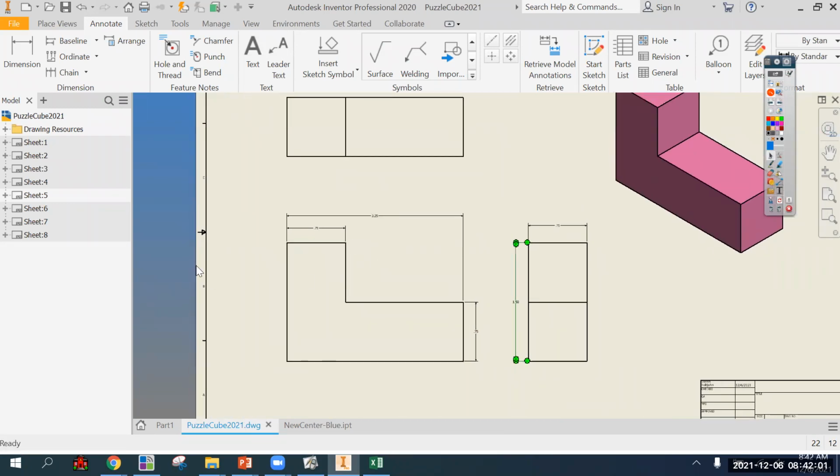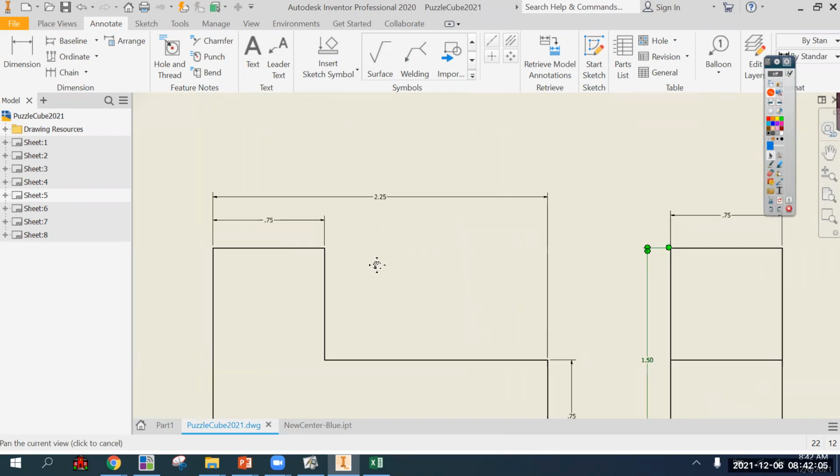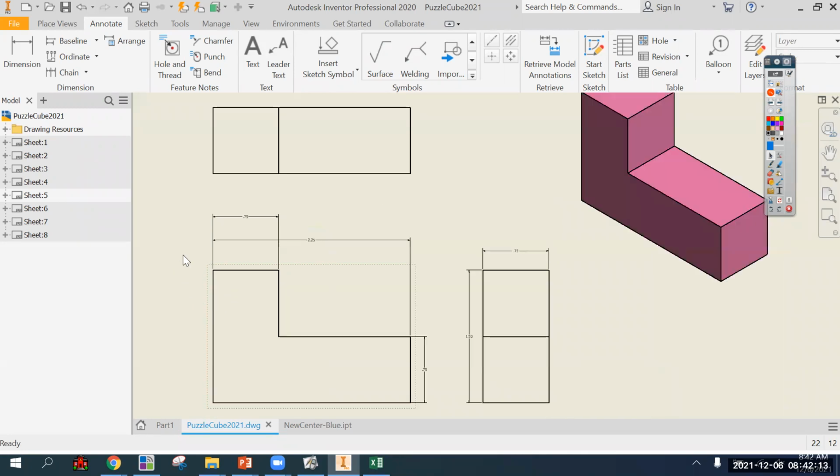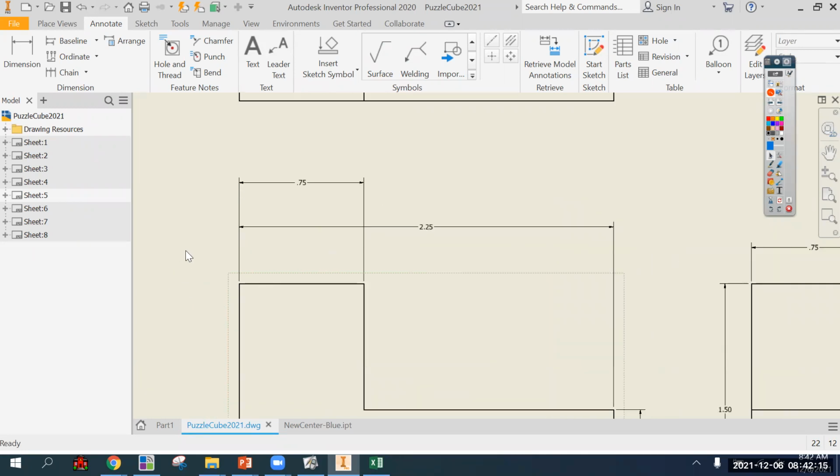So our method of working left to right every time something happens, take a dimension, will save you from a lot of mistakes, like having shorter dimensions outside longer dimensions. I mean, not knowing anything about dimensioning, you should be able to tell that that's wrong. It just looks weird. It kind of hurts my brain to look at a little bit.